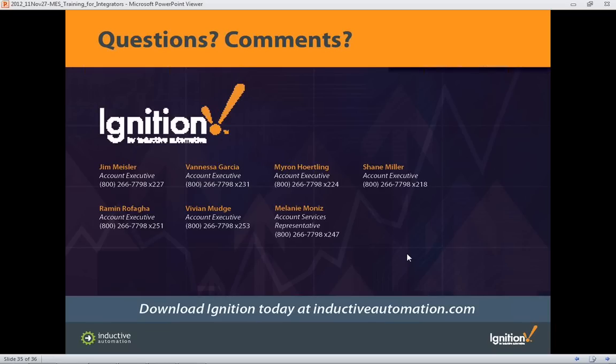Great, thanks, Tom. So here's one from Tim. How are we gathering this information on downtime? Is it completely automatic by being wired in directly to individual I/O points, or machines or processes? Both. We can tie into machines and detect automatically the state of the machine, and we're just reading a numeric value out of a PLC. So 0, the machine is either turned off or idle. 1 is it's running. 2 is down for a fault, or however you define those. You can define them. And so that's one method of doing it.